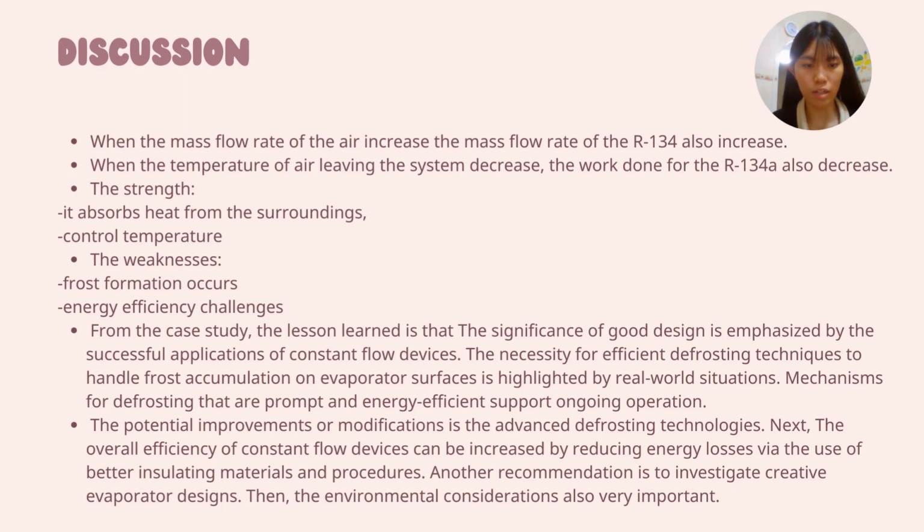The strength is that it absorbs heat from the surroundings to enable the phase change and maintain the low temperature for long-lasting food keeping and food preservation. The weakness is the frost formation. The weakness is that frost formation occurs in the evaporators in high humidity conditions. It will cause the heat transfer efficiency to reduce. Inefficient heat exchange will have an impact on the environment and increase energy exhaustion.